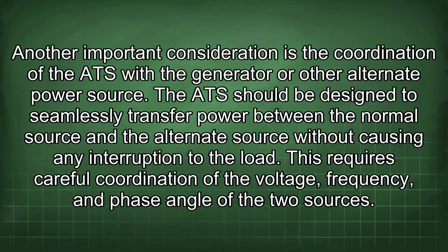Another important consideration is the coordination of the ATS with the generator or other alternate power source. The ATS should be designed to seamlessly transfer power between the normal source and the alternate source without causing any interruption to the load. This requires careful coordination of the voltage, frequency, and phase angle of the two sources.